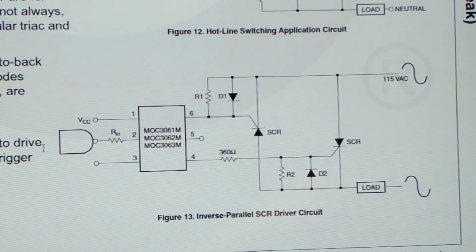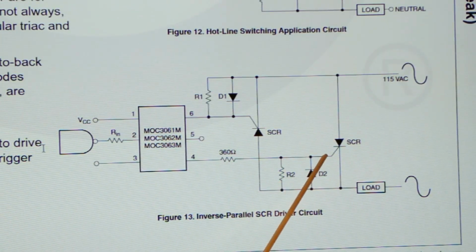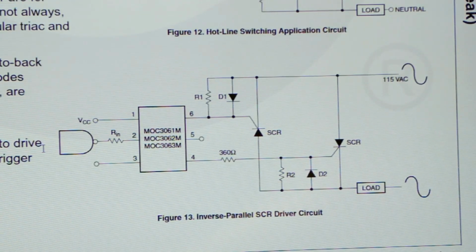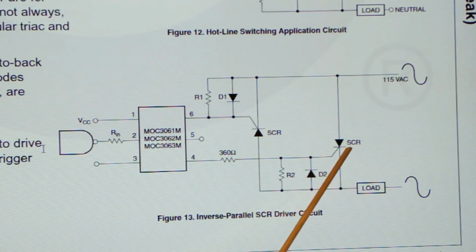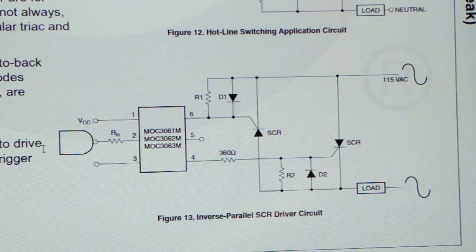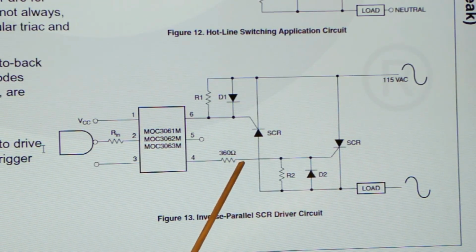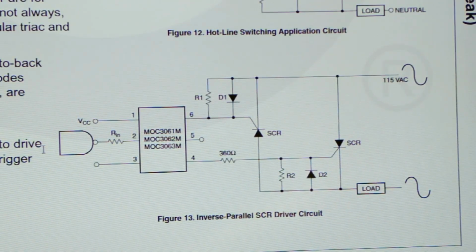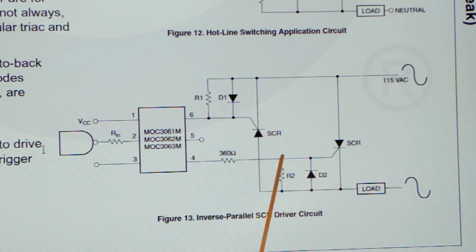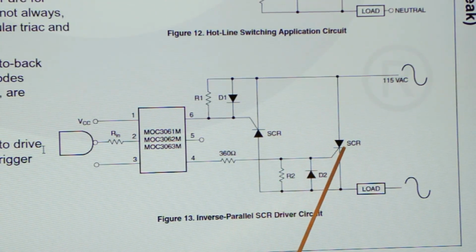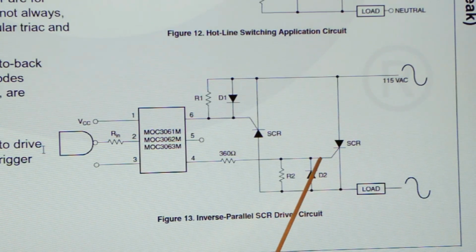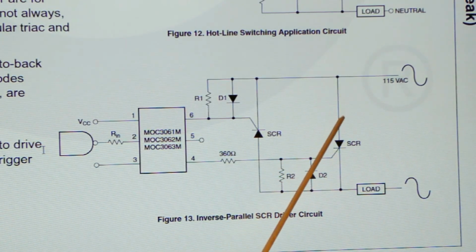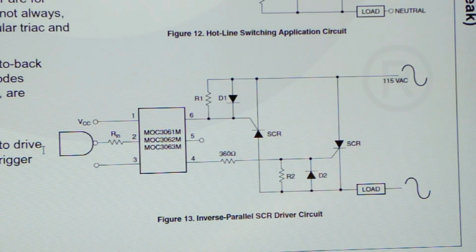So what I had to do to improve the switching, because I hooked up a current meter here at the gate, and it's drawing 14 milliamps, only 14 milliamps. And of course, once you start applying a load onto the transformer, then the switching comes better, and the current drops almost to nothing on the gate, because then the main current is being switched through the SCR.